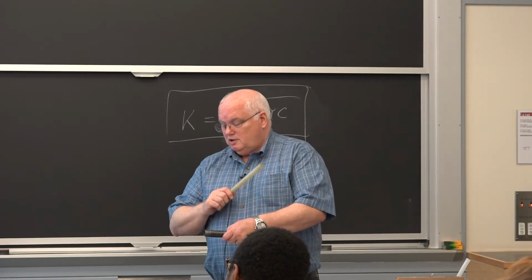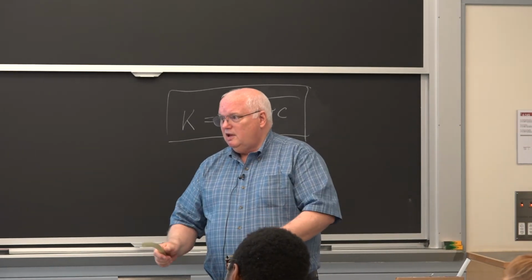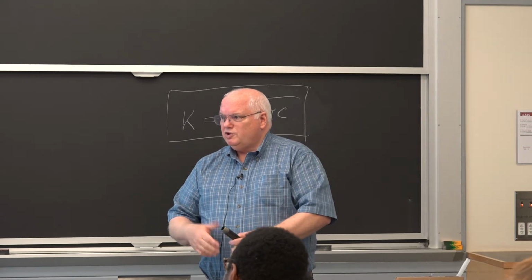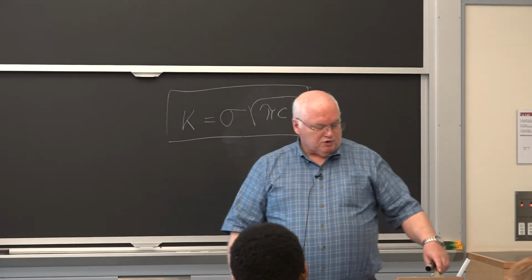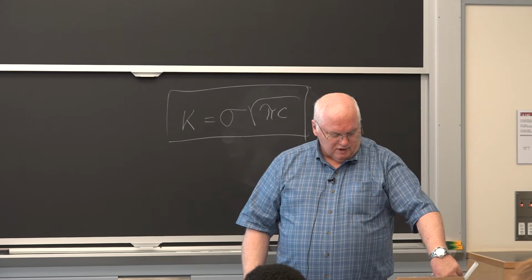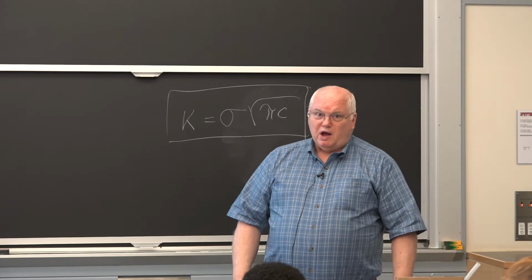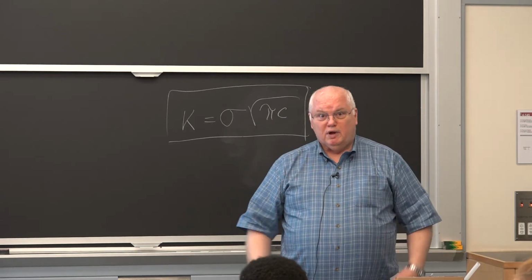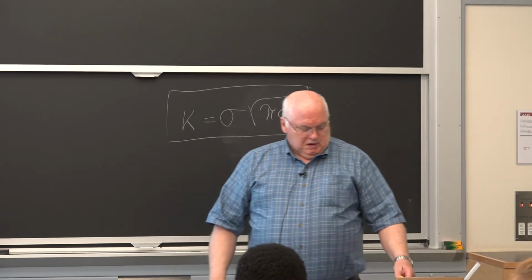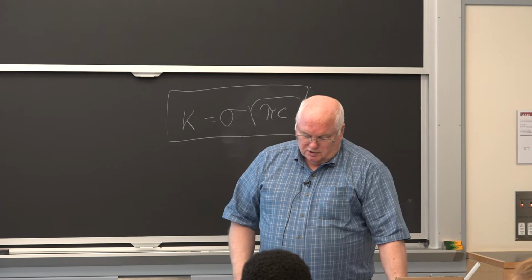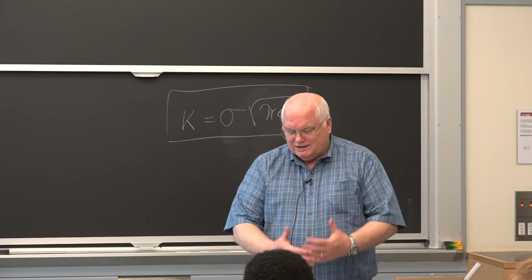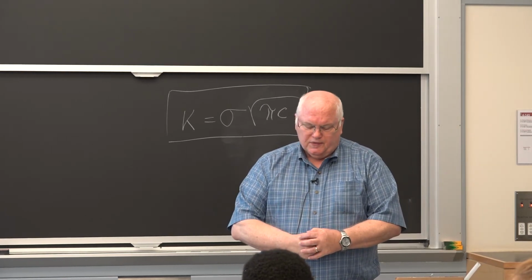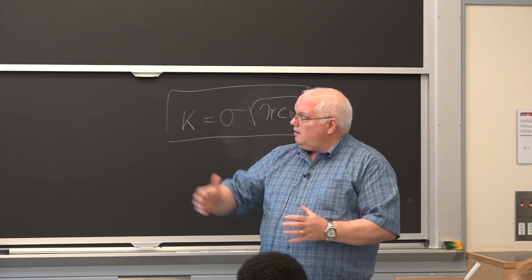You take copper even against a piece of steel, the high thermal conductivity won't generate the spark. You won't get the high temperatures because of the high thermal conductivity. And you don't want sparks in the bottom of a mine, where you could have a lot of gas and it could go kaboom and kill a lot of people. So for 10 times the price, you can get different strengths in different materials, but there are technological limits.